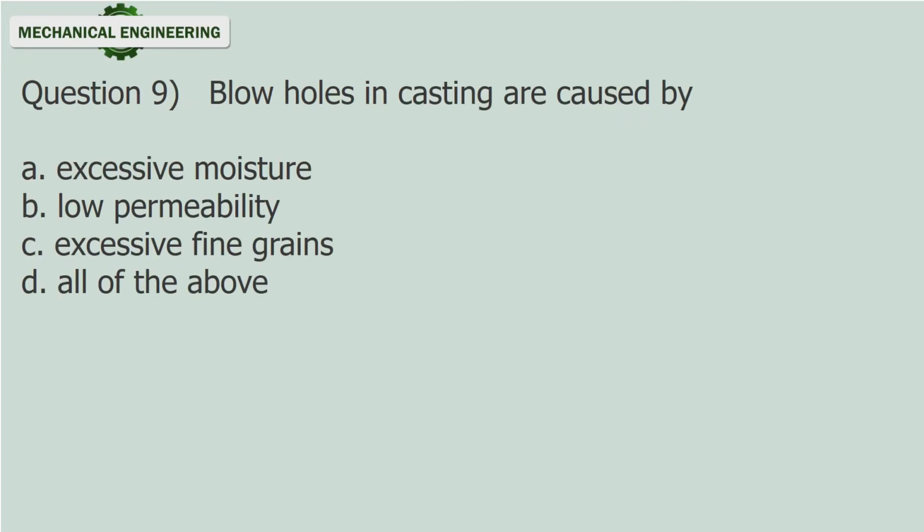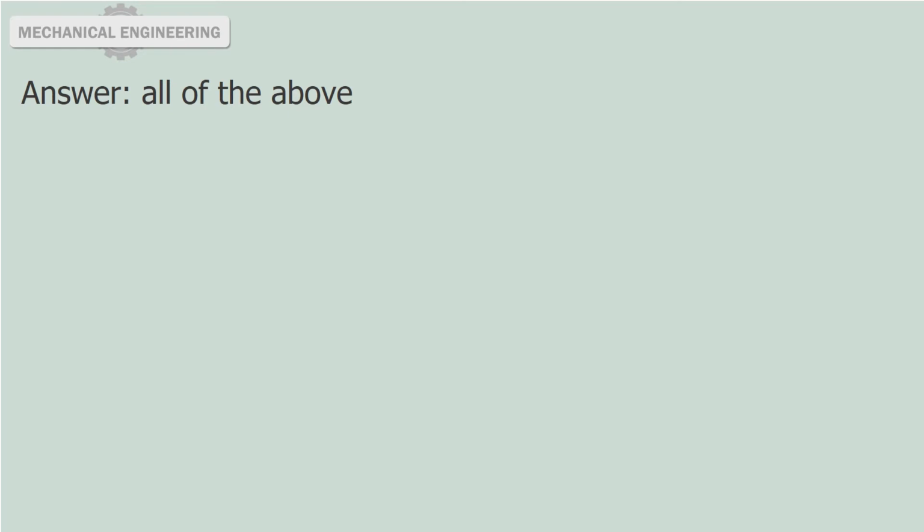Question 9. Blowholes in casting are caused by A. Excessive moisture. B. Low permeability. C. Excessive fine grains. D. All of the above. Answer: all of the above.